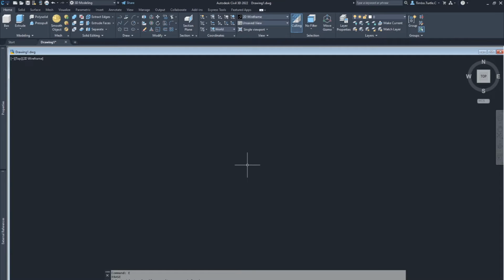But there are some pretty basic lines. Now, you can learn the very basics of AutoCAD in 20 minutes or so. You just think, if you want to draw a line, type in L for line. You'll see in these later versions of AutoCAD, it'll give you all the commands that start with L. So you can go Line, and you'll get a line. Obviously, easy enough. You'll see when you start to draw the line, and you click on any point, you'll see the length. If you want that to be a specific thing, just type in the length, and it will draw a line that long. Pretty straightforward, really. There are some other tricks of the trade to get to, but I'm just giving you the general basics.